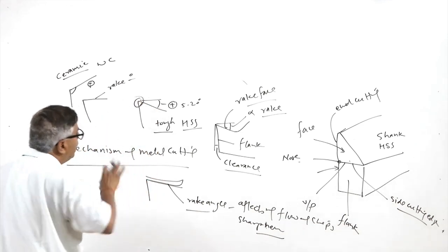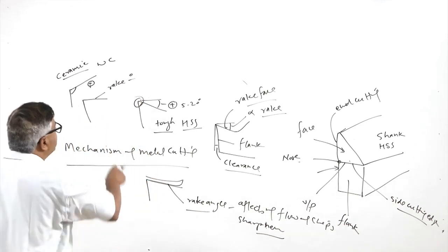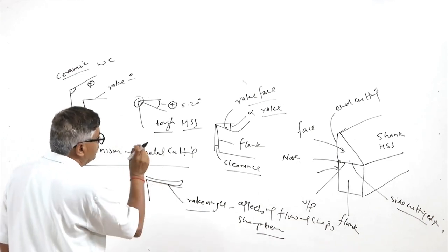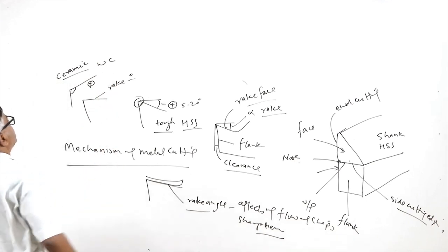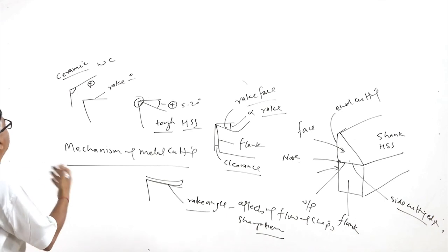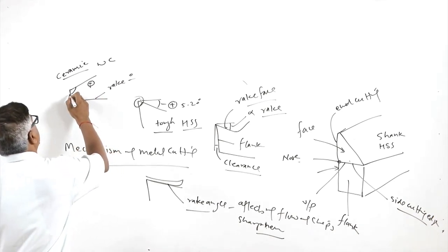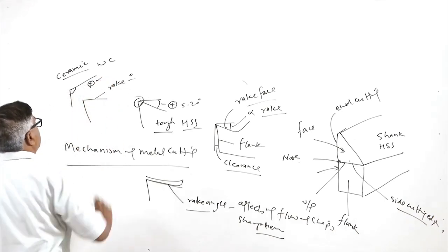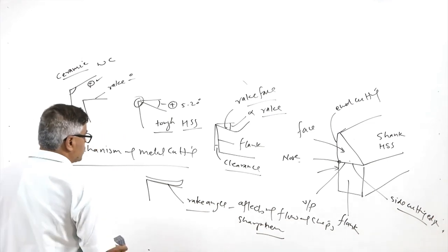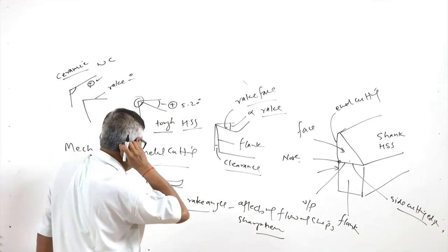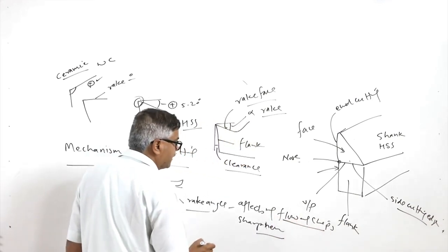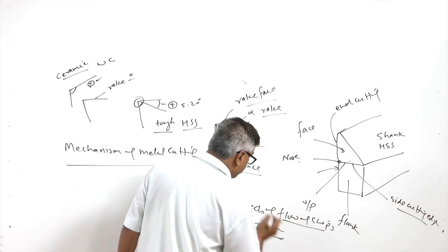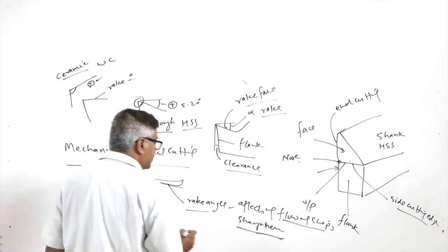Tough tools allow machining by the cutting edge even with limited cross sectional area, and ceramic and tungsten carbide tools, which have low toughness and high hardness, can work efficiently with negative rake only. So, the purpose of providing rake angle is to have the proper flow of the chips after getting removed, and to have the proper sharpness of the cutting edge.